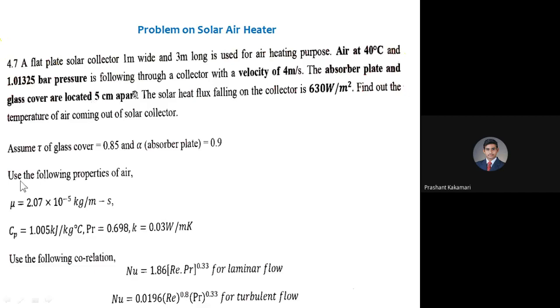So now to find out the temperature, I think you can assume that when the air is moving between the plates or above the plate, the air is going to collect or absorb the heat by the convection process. Okay. So for the convection process or any other process, we know a formula from the heat transfer subject. For heat gained by any fluid, I can write Q equal to hA into delta T.